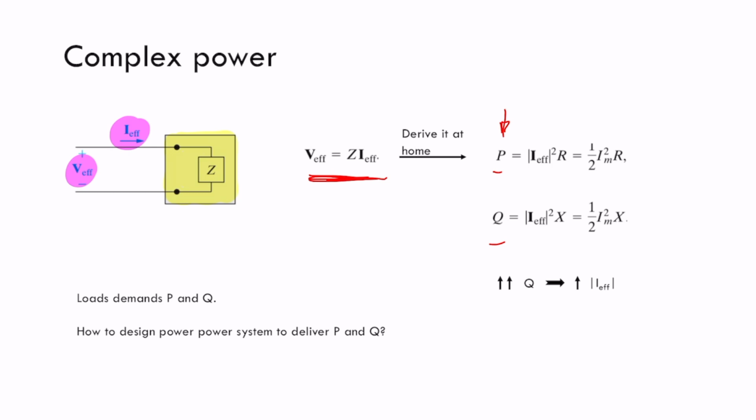But the important thing is that if you replace that, you see the active power is a function of one half of the current squared, the amplitude of this signal, whatever the signal, squared. So this will always be positive, times R. It means the active power depends on the square of the current. Below, the reactive power also depends on the square of the current.